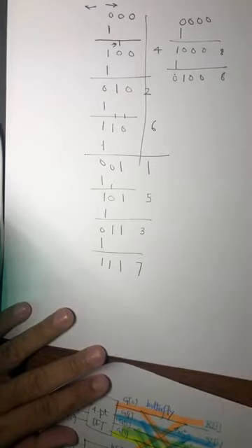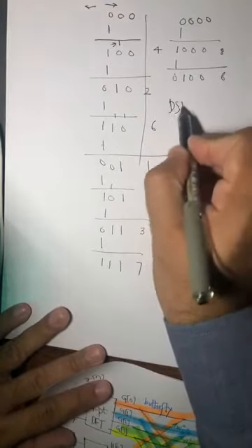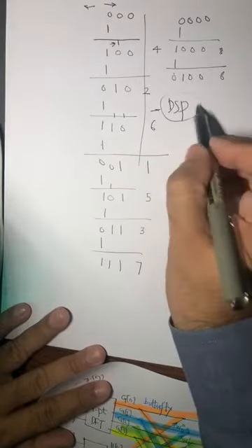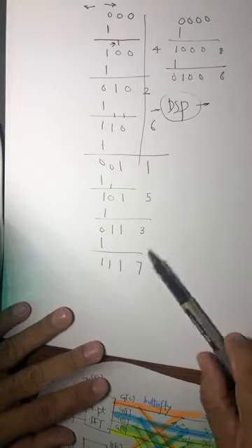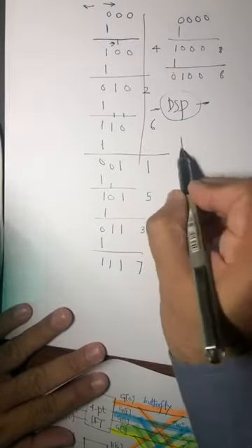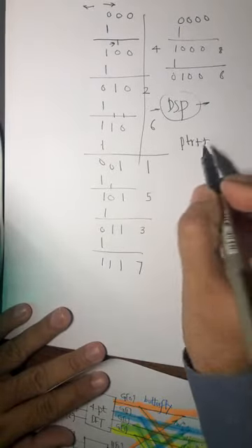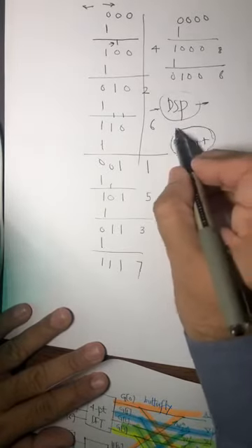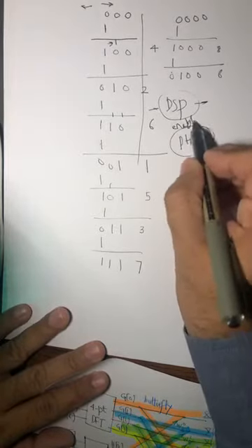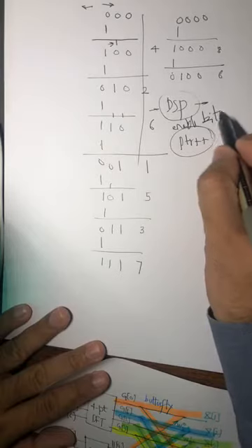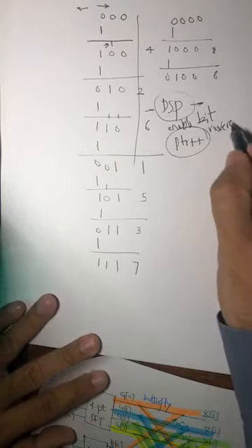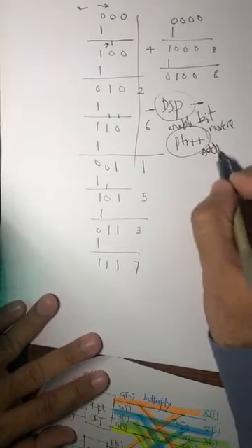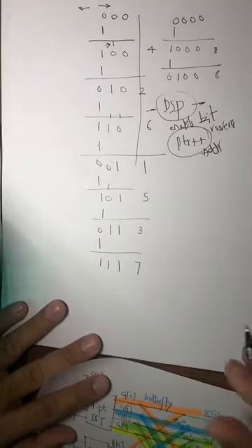So every digital signal processor, every chip you buy, including the one you are using in the lab, has a bit reverse addressing mode. If you enable that and you say pointer plus plus, pointer plus plus, and enable bit reverse addressing. It is called bit reverse addressing. There is a mode in digital signal processors.